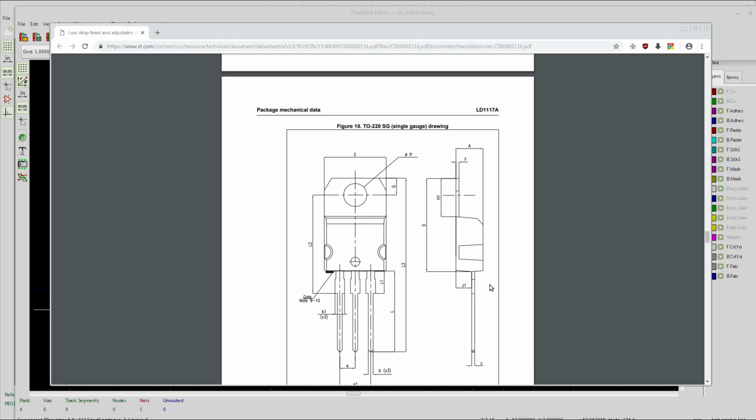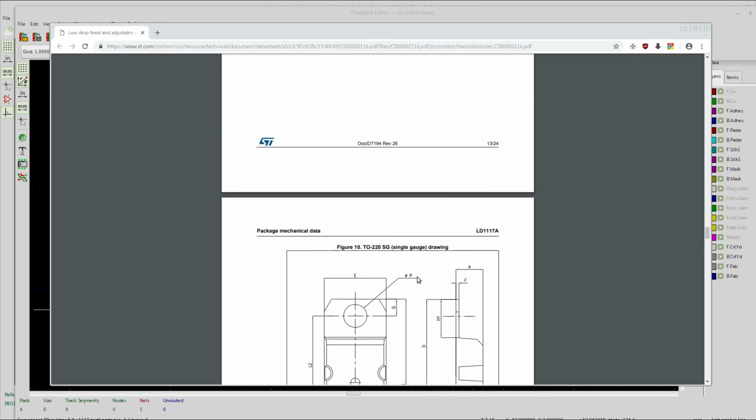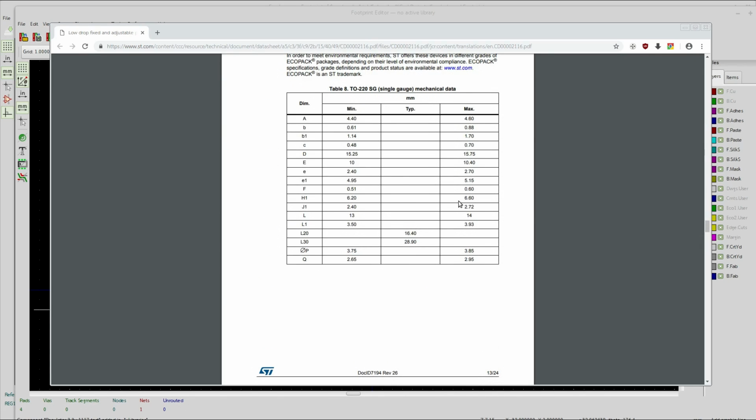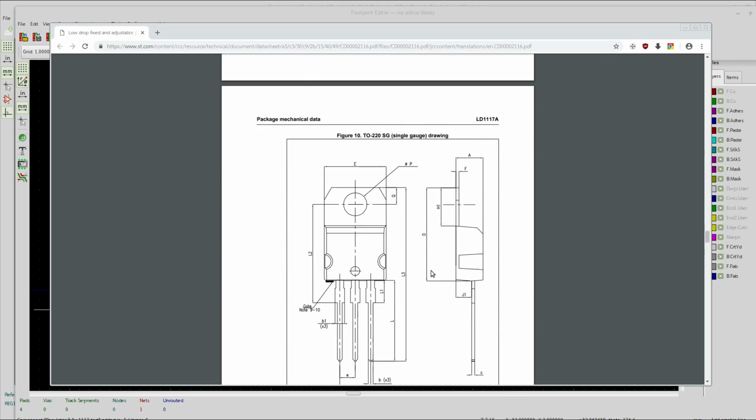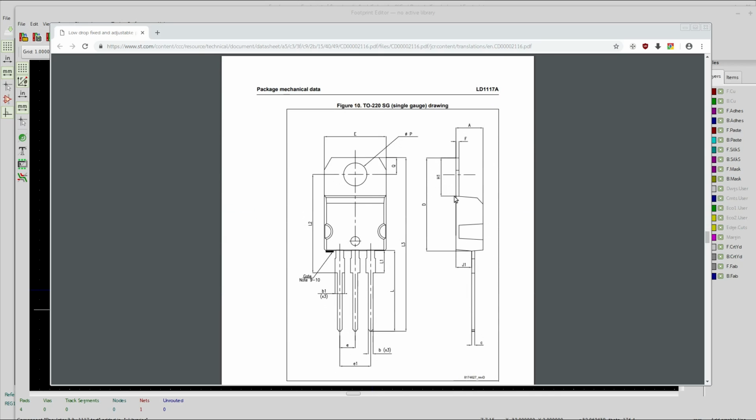And we're keying everything off of the holes that we place. So we've got to make at least a pretty good assumption on what this extra value is right here. We've been saying it's like 1.5 millimeters or 2, we could say 2 millimeters, that it's going to stick out after it's bent. So for example, let's try to attack H1. So H1 is, let's say, 6.5 millimeters, so 6.5 millimeters from the top here.